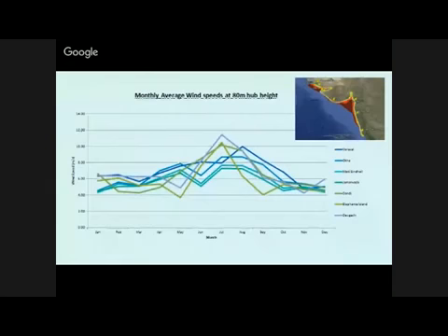This is the data available near the coastal area of Gujarat. There are five or six locations: Veraval, Oka, Dandi, and Devgarh. Based upon the in situ measured data, we have converted them using the log-log law into monthly average wind speeds at 80-meter hub height, and wind speeds for different months are shown. Now look at the